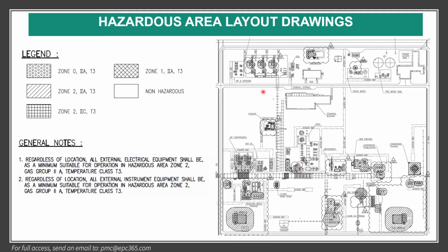If the restricted area goes through this area, that means if there is a source of release here, the gas can go here. So here the air intake should have 2 out of 3 gas detectors. In case of detection of gas releases here, they have to close the dampers.